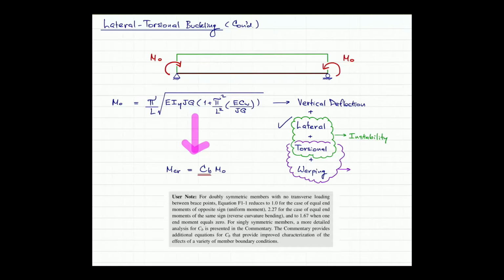It is intended to resist the gravity vertical load, and then you are supposed to have only the vertical deflection. But this lateral deflection comes when it loses stability, and we derive all this expression from the deformed configuration, and we look into the deformed axis of the cross section of the beam.